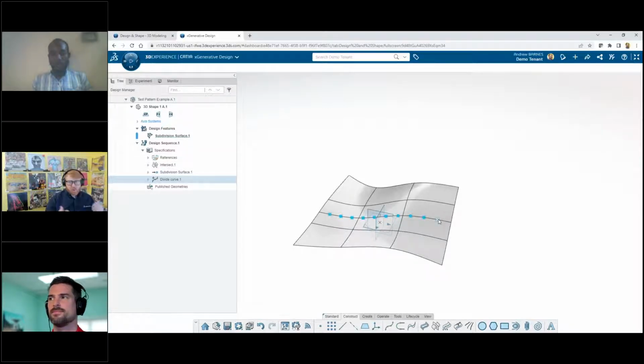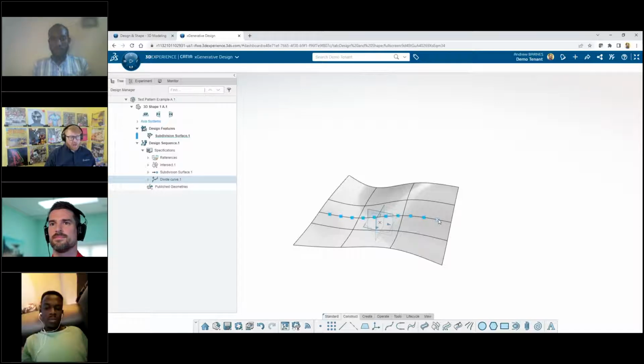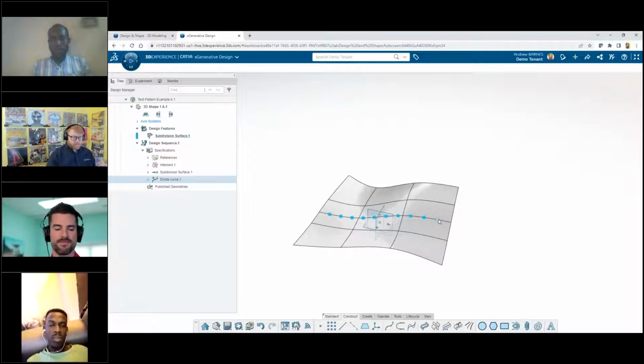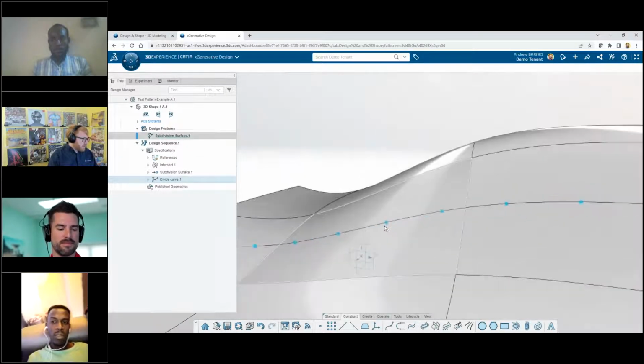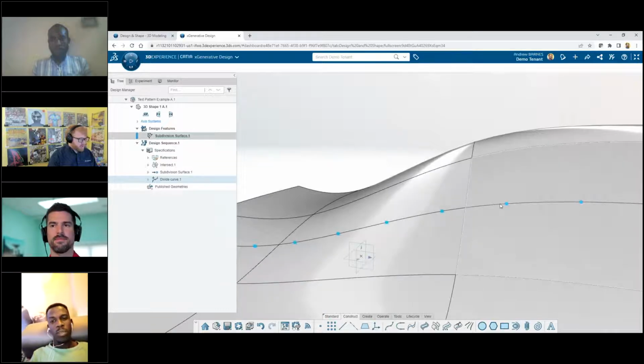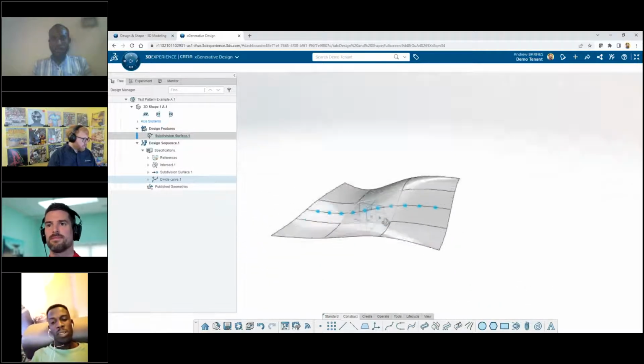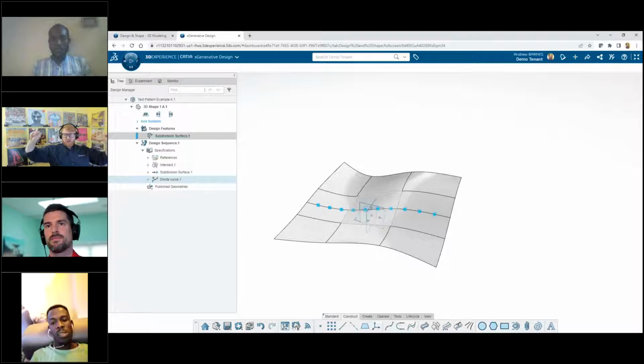We actually have a tool in SolidWorks that's very similar, called the segment tool. You search in your command search for segment, and you can place points on the curve, or even segment them out. But this also takes into account the curvature, so they're all the same curve length. It's almost like a string you could straighten out and they'd all be even.